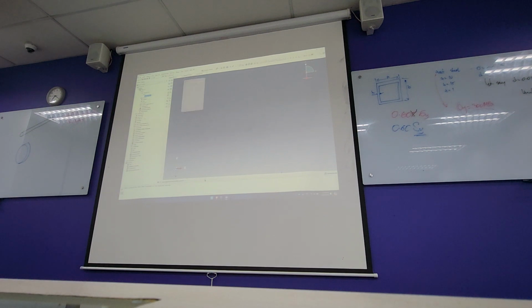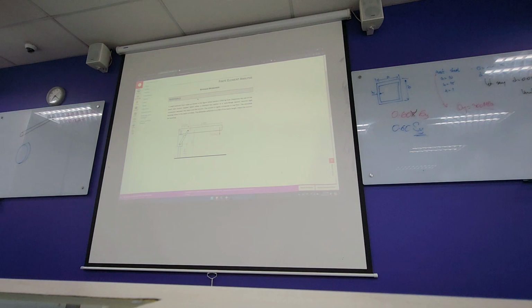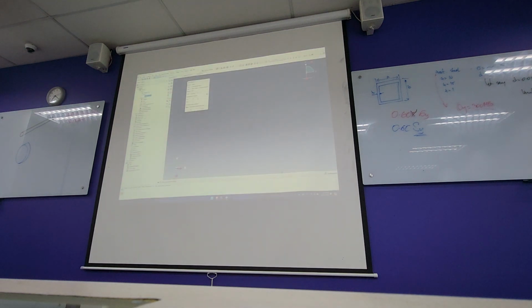Sigma Y is the beam. This is to determine the design. No, yeah, it's the stress. That means, let's say you're using steel, right? The yield stress is 800 megapascals, so you need to use 800 times 0.6. Then when you calculate your stress, your stress cannot exceed that 480 megapascals.